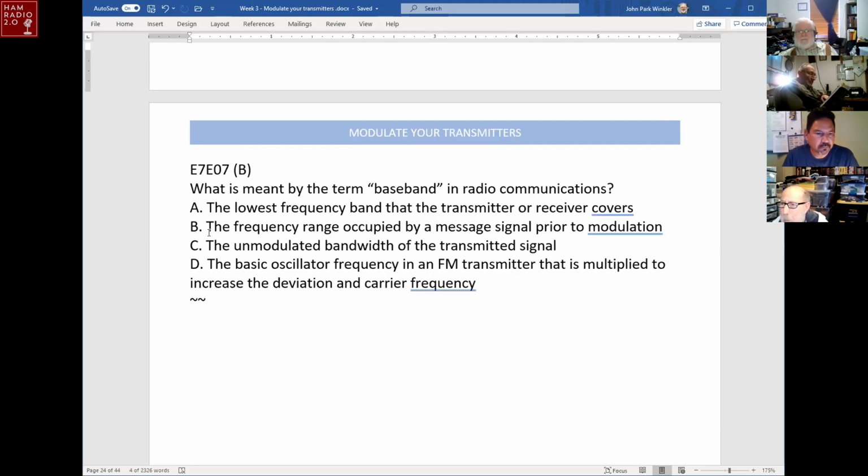They're talking about two different things. They're talking about the frequency of the audio signal. We'll have to spend a little more time on the definitions of baseband and bandwidth. Baseband would be, for example, just in terms of simple audio, not talking about additional subcarrier frequencies, just the baseband of a simple audio signal. If you're talking along and your speech is going to be in the 200 to 3,000 hertz range, that would be the baseband.